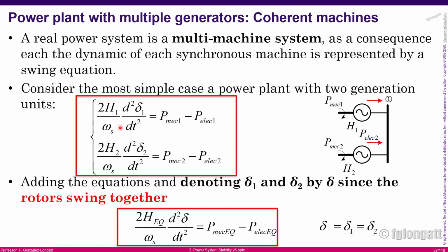is referred to the synchronous reference, okay? What I'm trying to say is that those angles are measured against a reference, and that is the synchronous reference, a vector that is rotated at synchronous speed, and all the angles are referred to that angle.